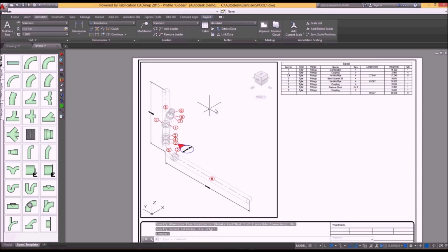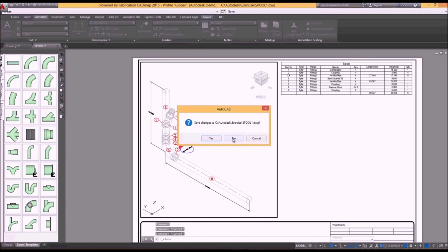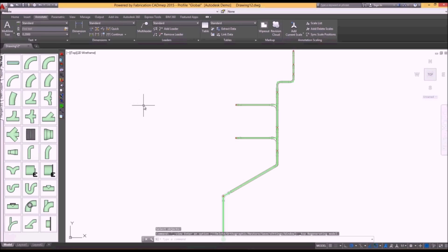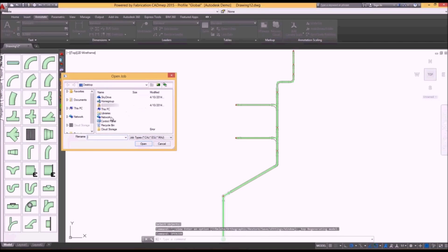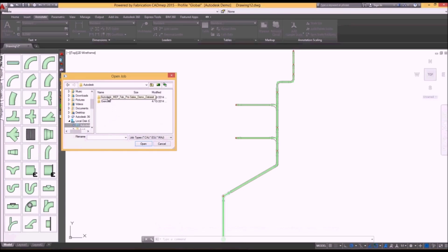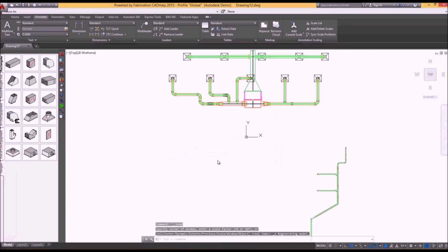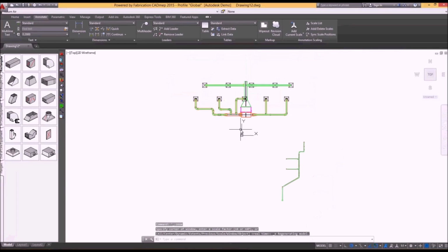Okay, so we took parts of our drawing, and we used that define spool tool where we made a separate layout in another drawing where we used that as a detail. We could even open up multiple jobs together where we're laying them out within the same drawing. So I'm just opening up this one real fast. Hit OK. If I zoom out, you'll see what happens. See how it just laid them both in the same drawing.